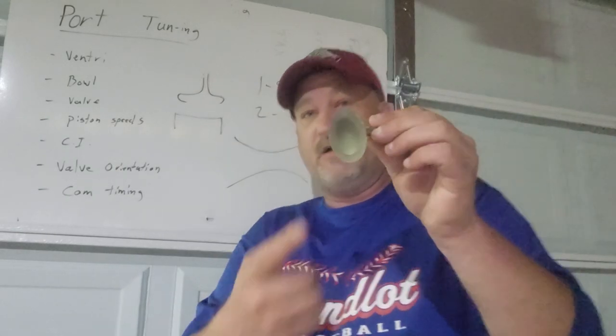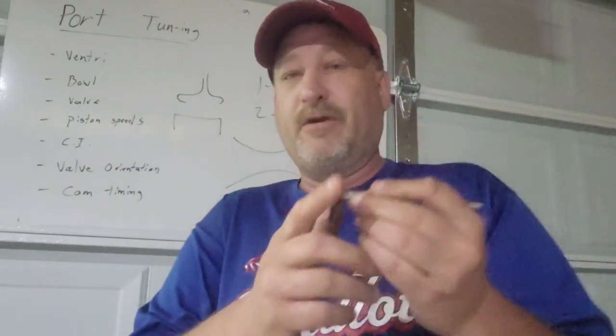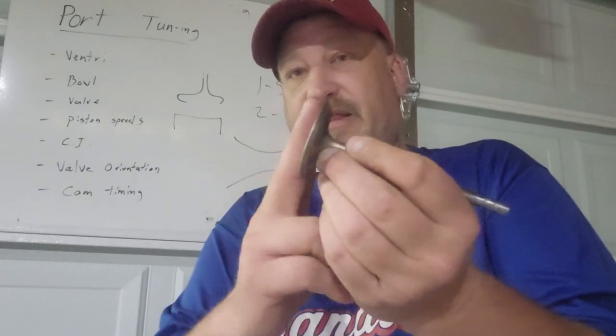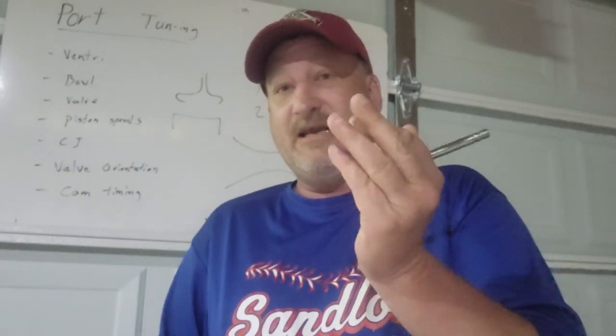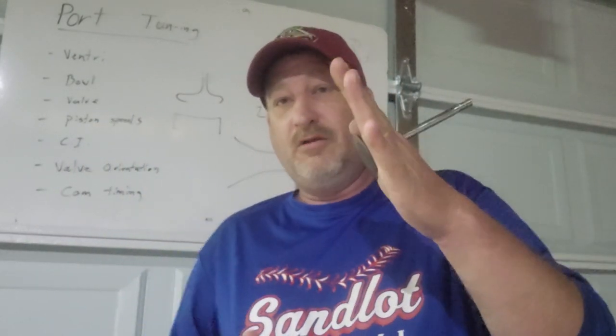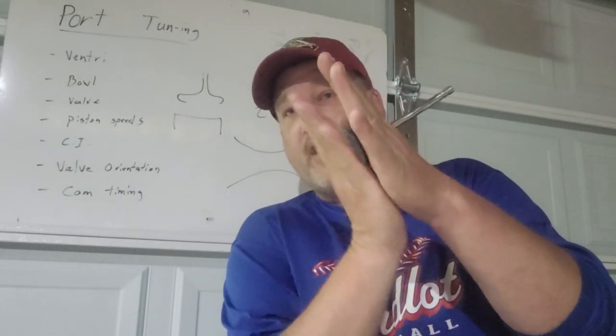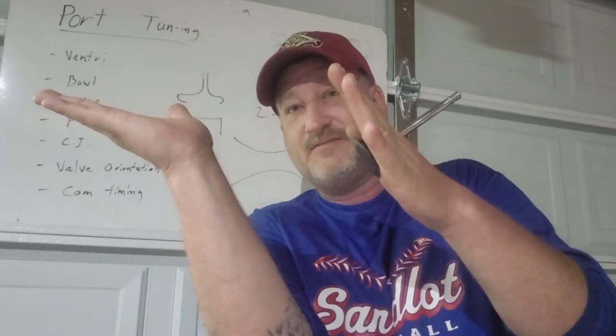And they will have different styles of valves. Normally, the big block Chevy with a cant, or any canted valve cylinder head, will have a flat faced valve, because once mated up to the seat, it creates a wall for the air to basically be pushed up from the piston and directed towards the exhaust.